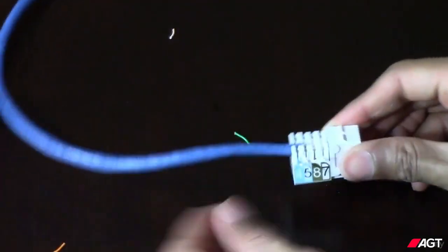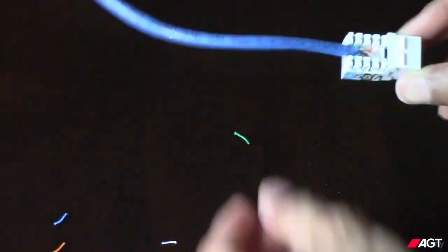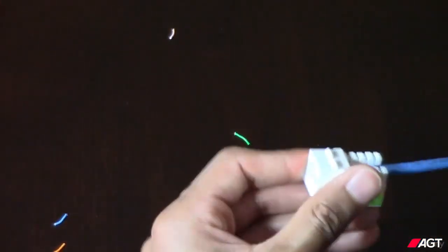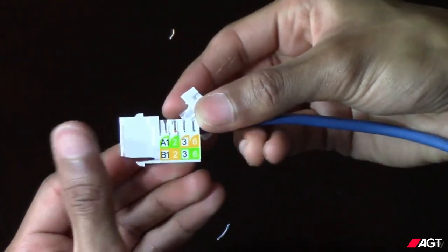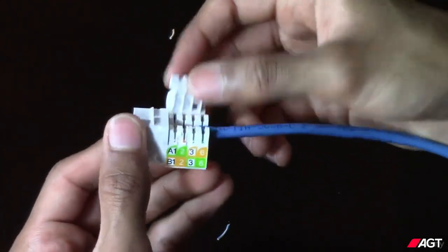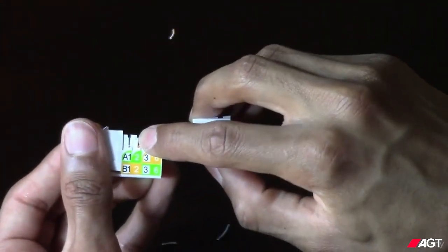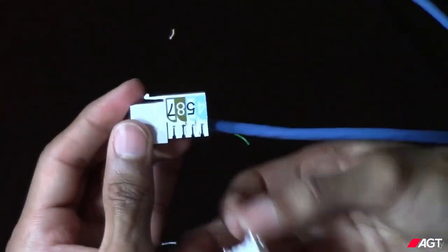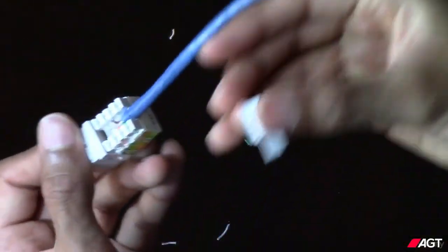Once you've punched down all the wires into their ports, rub off any excess wires and you're pretty much done with the jack. The last thing you'll want to do is cover all these exposed wires. Your jack should come with a cover like this. All you really have to do is secure it over the wires. There will be two tabs on each side to receive the cover. Here and here. But before I fasten this cover, I want to test the jack to make sure it works.